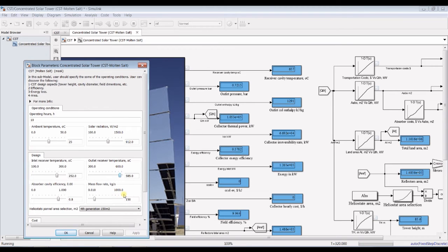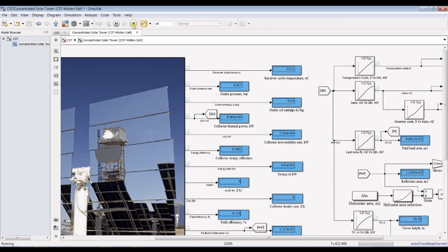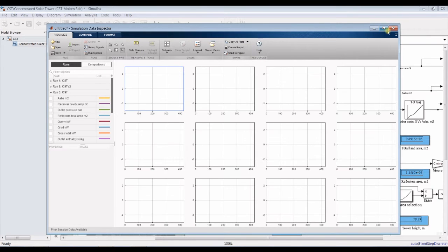As you can see here, let's go down in order to watch the effect. Going down again, and the absorber efficiency I will increase up to 0.9, 90%. Okay, and stop our simulation. Fine. Let's go under the case of infinity, click here and see our data inspector results.